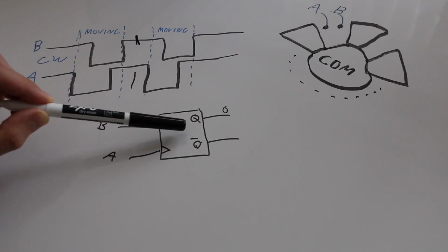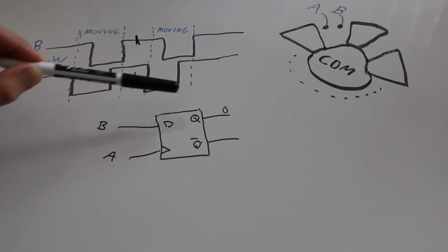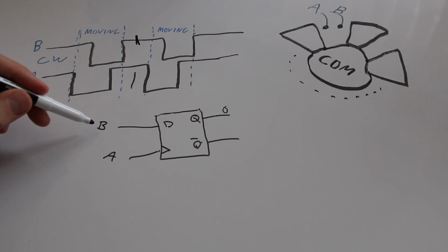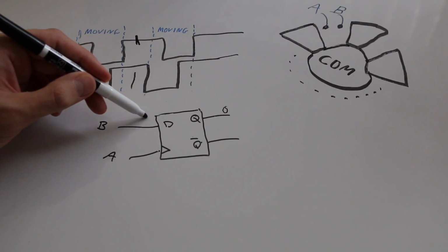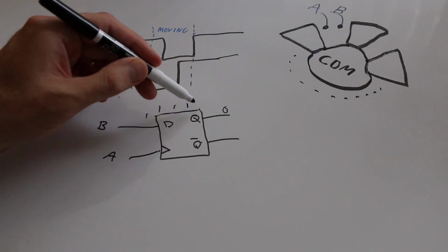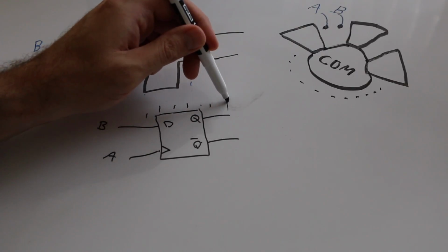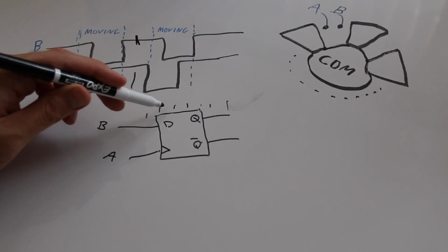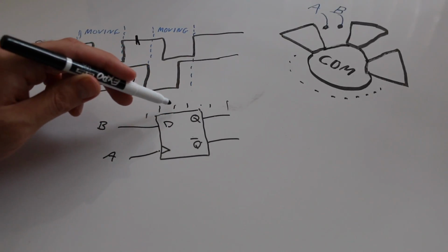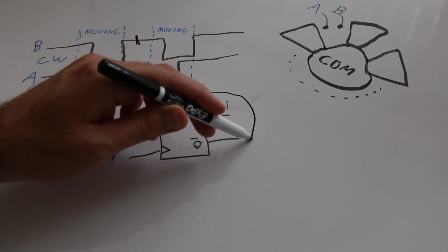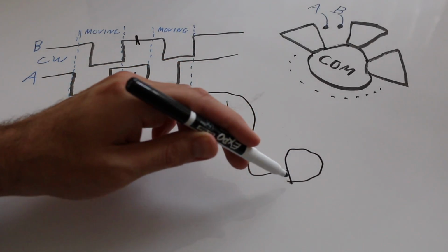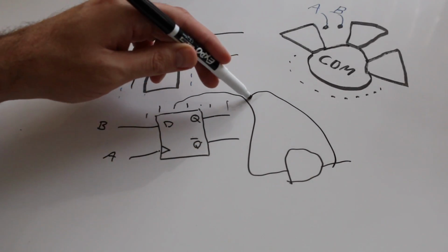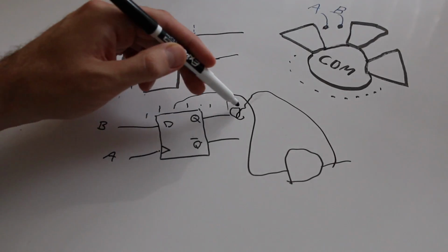But has this flip-flop had enough time to propagate B to Q? This might be going counterclockwise suddenly, so there's a logic 1 on its way through the flip-flop. Eventually the 1 makes it out as valid data, but in the meantime, while this was happening, you still have a 0. Somewhere around this point in time, your other circuit sees the clock and says, oh, let's check the data. It was 0 because you haven't updated yet.